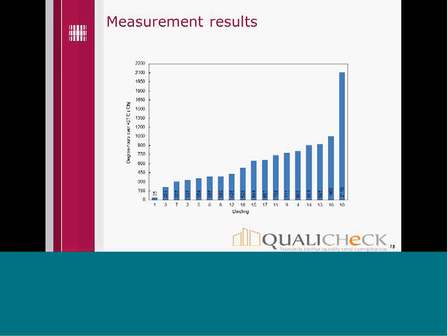Then we also calculated these excess hours as degree hours over 27 for all measured dwellings, and we can see much higher values than the limit value to be used in the simulations, 150. Only one apartment was below, and the second one was quite close to the limit that applies for the test reference year and for the temperature simulation procedure. So during that warm summer there was quite a lot of overheating in almost all apartments.